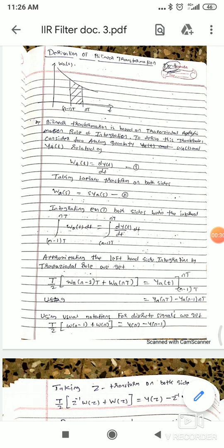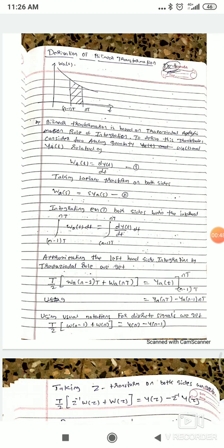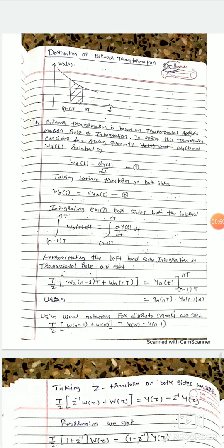So this is all the procedure. First thing is, here we have to design an analog filter and then we convert that into a digital filter. So design the required analog filter first. It may be Butterworth or it may be Chebyshev. Once you get the transfer function of the required analog filter, then you can convert that into a digital filter. This process we call S to Z plane mapping, right? S to Z plane mapping.